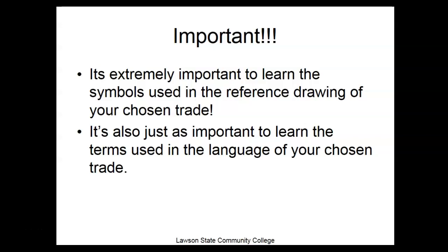We had one guy that chose transformers. And he said transformers step power up and down. Well, transformers don't step power up and down. Power in equals power out if the transformer were 100% efficient. Transformers don't create power, they just control power. So as soon as he said transformers step power up and step power down, he lost the job because he didn't know the language of the trade. He didn't know that transformers step voltage up and step voltage down, but power in equals power out if the transformer is 100% efficient. So learning that is very important.